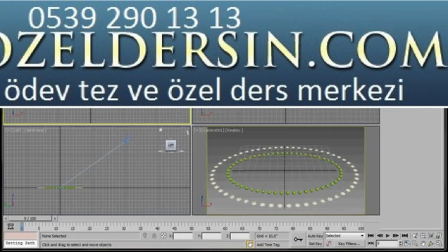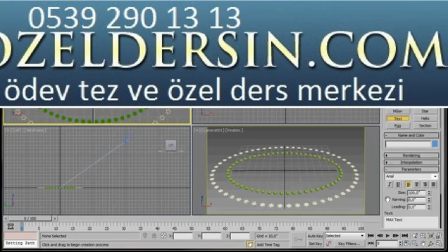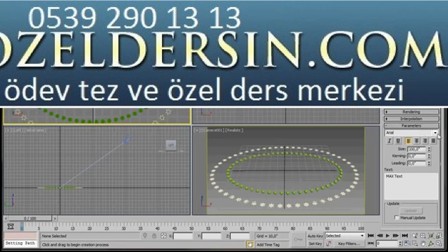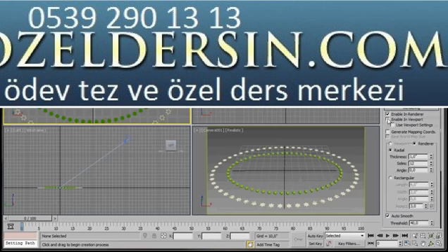We're going to do that in the top viewport. So I'm just going to zoom in here a little. Then I'll go over to the Create panel, Shapes, and select Text. Let's just scroll down a minute. Now here we're going to change our font. Let's select an Arial Black Normal font. We'll go up to Rendering. I'm going to enable in Renderer and enable in Viewport.